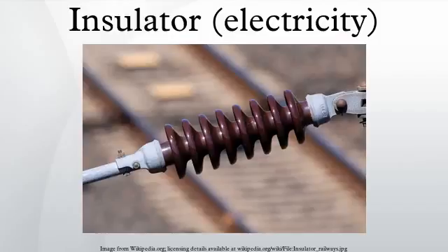the electric field is not distributed evenly across the string but is strongest at the disc nearest to the conductor, which flashes over first. Metal grading rings are sometimes added around the disc at the high voltage end, to reduce the electric field across that disc and improve flashover voltage.